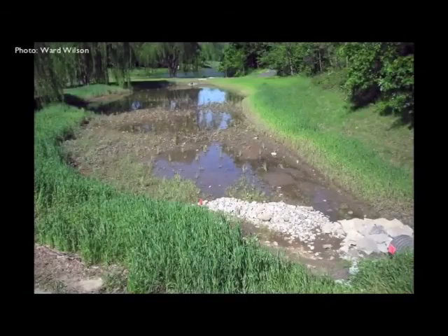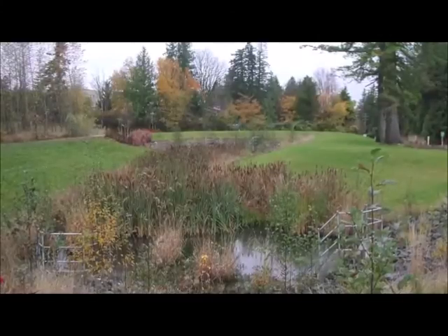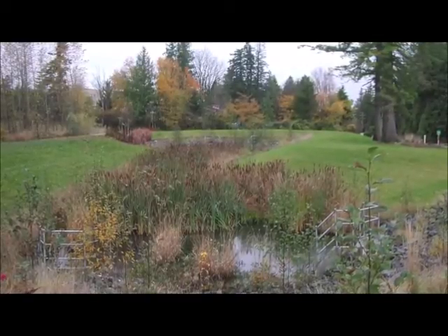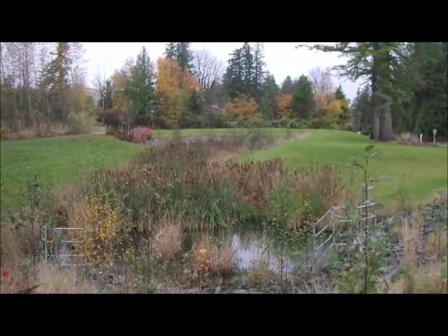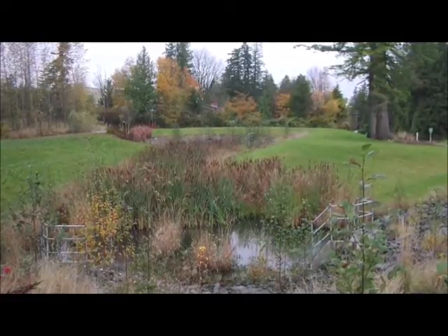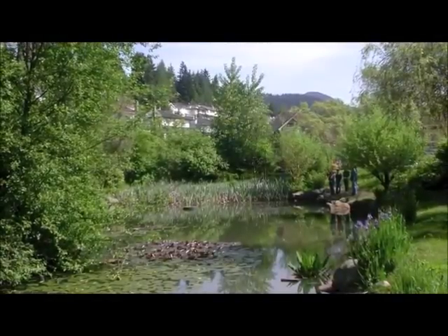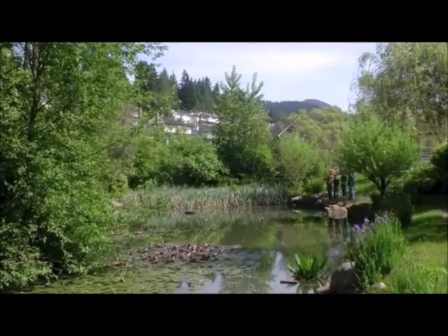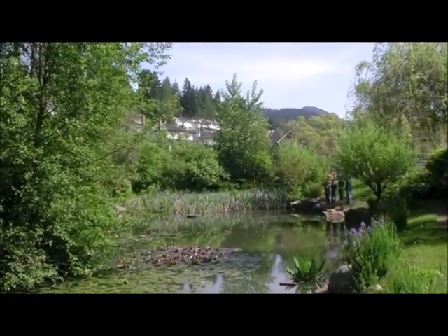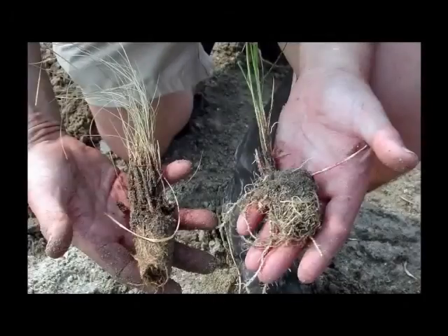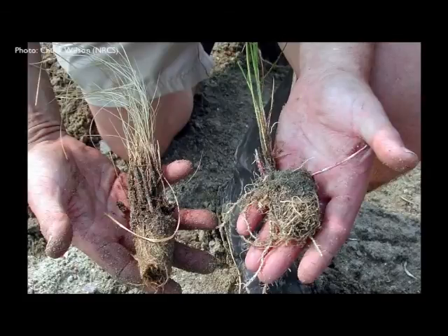A proper design for wetlands includes a forebay that serves as a deposition area for sediments, which can be removed on a regular basis. This assures that clogging of wetlands is minimized, nutrient and dissolved metal uptake is maximized, and some degradation of hydrocarbons and pathogen reduction can take place within the wetland. Regular harvesting and replanting of new wetland vegetation is required to maintain efficiency.